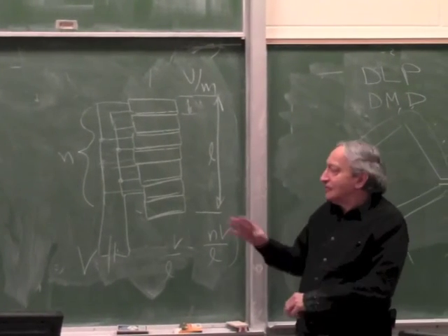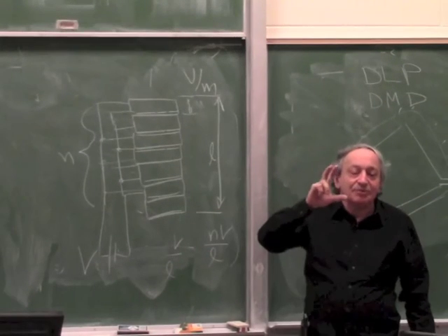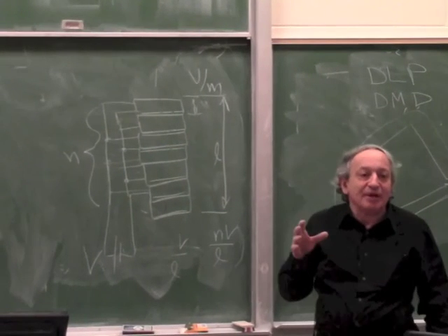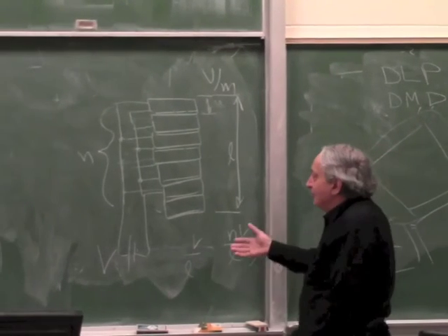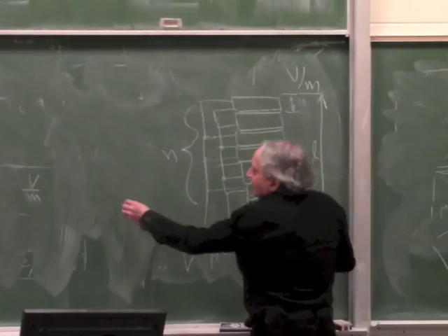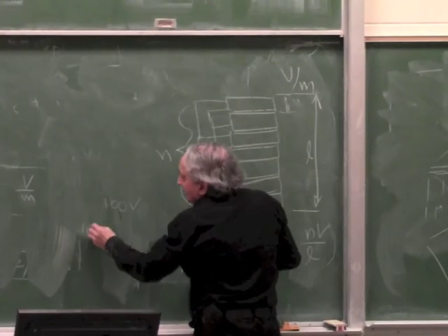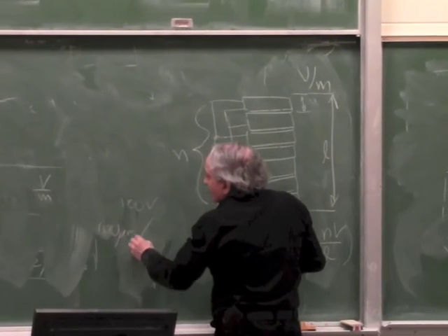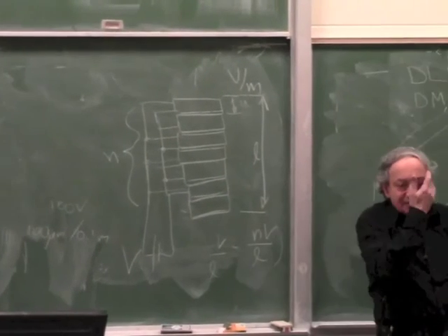Okay, so this solves the first problem. Now, if you have a stack about 10 centimeters long, you can move 100 micron with a reasonable voltage. Take a good number of today's stacks like this: if you give it 100 volts, you can move maybe 100 micron over a 0.1 meter stack. It's a typical performance number.